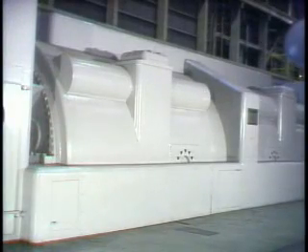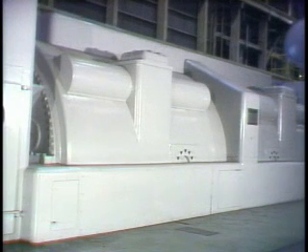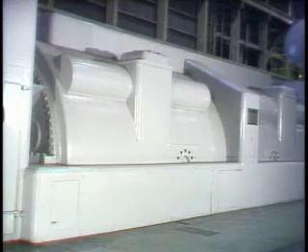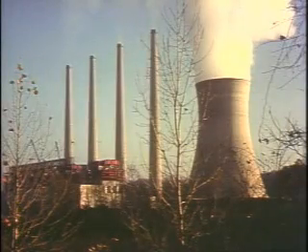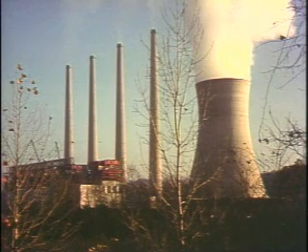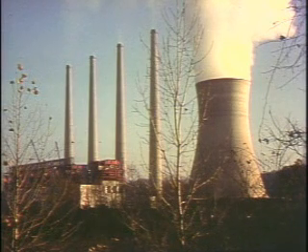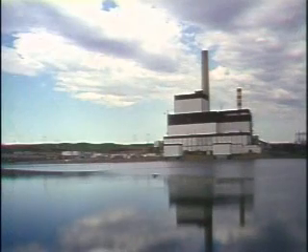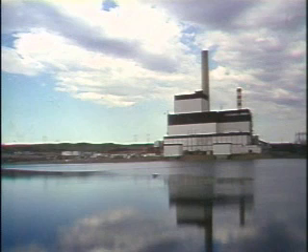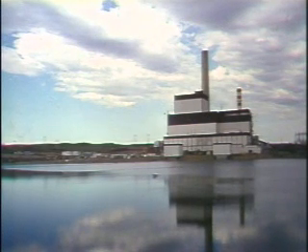The two types of systems that are generally used to deal with the hot water produced in the tubes of the hydrogen coolers are closed systems and open systems. In a closed system, the hot water from the coolers is directed to another set of heat exchangers, where the heat is removed. Then the cooled water is recirculated to the hydrogen coolers. When an open system is used to provide cooling water, the heated water is returned to its source, which is often a lake or a river.